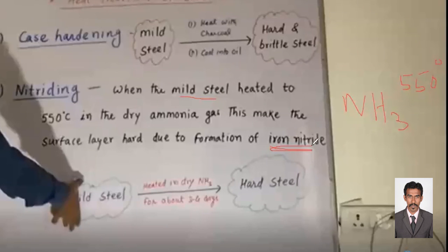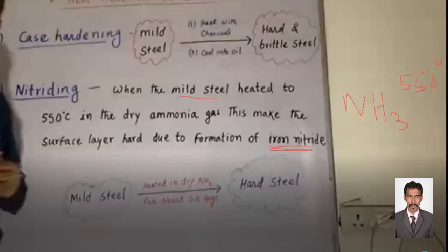So these are the differences between heat treatment processes. We have annealing, which is slow cooling. We have quenching or hardening, that is fast cooling. And we have tempering, which is fast cooling, then slow heating and slow cooling. What is the difference between hardening and annealing?